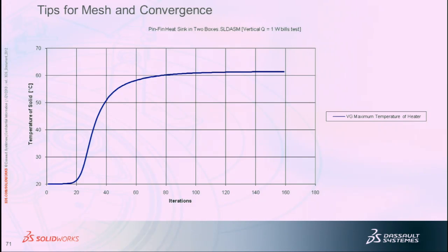No problem. Yes? I do a lot of simulations with particle tracking. I introduce particles as a source and then track them through the model, and I select the surface and measure the mass accumulation rate, the particles touching that surface. I'm interested in goal optimization, because I'm trying to make particles not land on a certain surface. So I wonder if there's a way, as an output option, for it to run the particle study as part of the solution, and use that to optimize the flow.